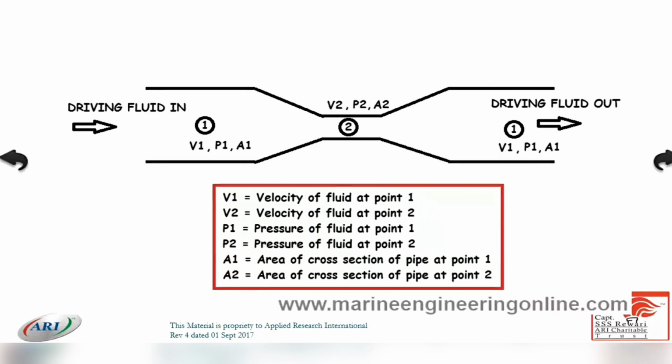Because of the double bottom, as we said, we have a double skin all around the cargo area. What they have done, all the strengthening, all the longitudinals, all the transverses are on the ballast tank side. The cargo tank looks like a room, no obstructions at all. Plain wall, maybe a corrugated bulkhead, but no obstructions at all. The bottom is flat, no longitudinals inside the cargo tank, because all the stiffening is done on the other side of the plate towards the ballast side.